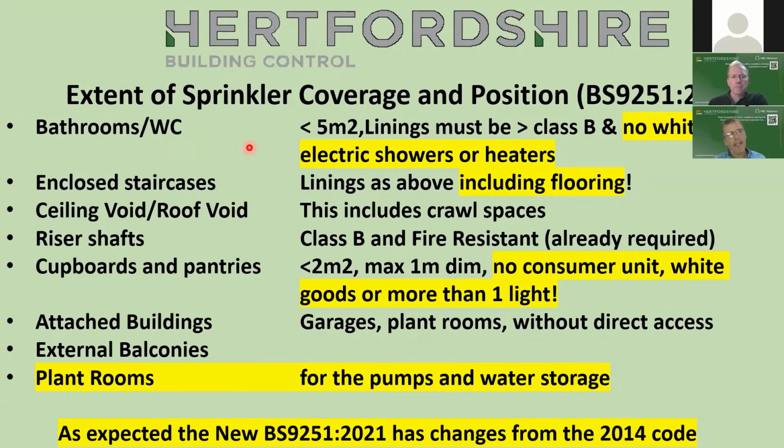What used to be the case is bathrooms under 5 square meters were exempt, didn't need a sprinkler head. But now, if there's white goods in them, because people are putting washing machines in the bathroom, if there's white goods, electric showers or heaters, they need a sprinkler head.